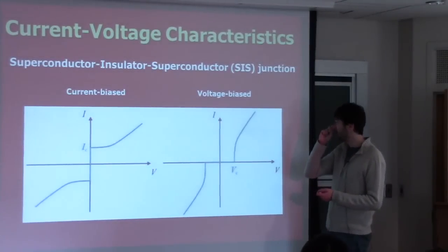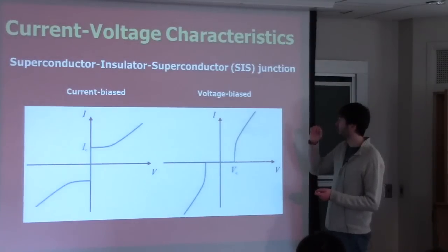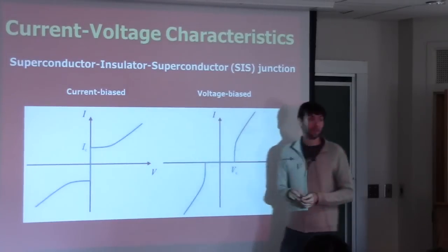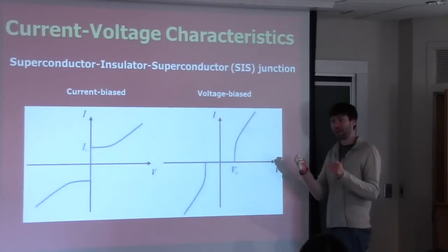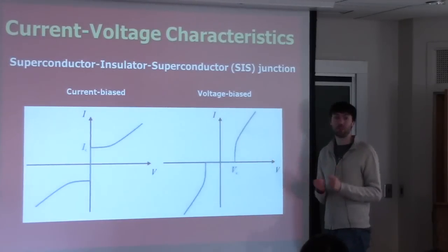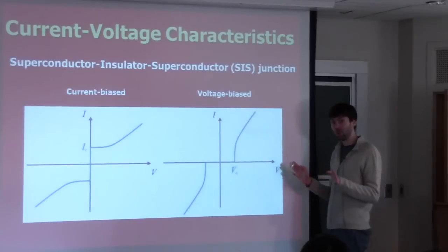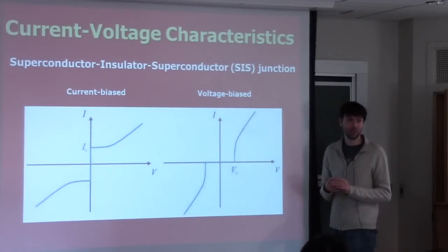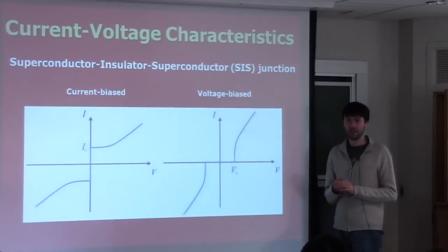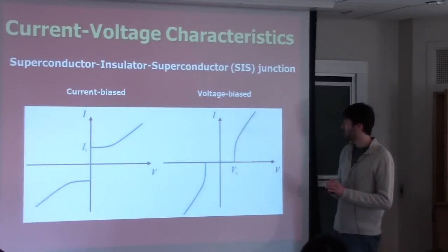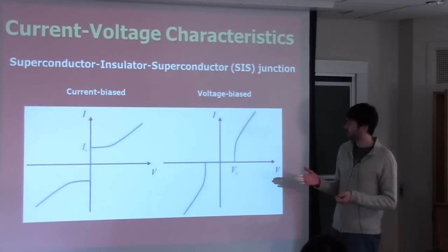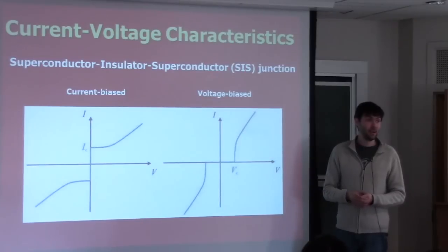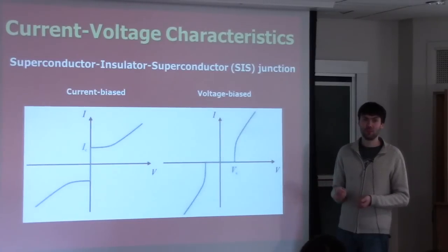And that is related to the fact that there is, again, this tunneling barrier. And to overcome a tunneling barrier requires a certain voltage. I will not go into more details of this because the story deserves a separate lecture in principle, and I might actually do that. But I just wanted you to stare with me at this data and appreciate how different this is from Ohm's law.